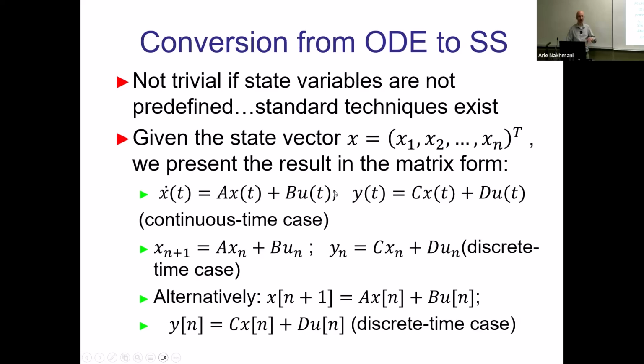This is how we will describe all of the systems, which is practically a system of first order differential equations, okay? You have n differential equations of first order, and all of them are linear. And the output will be computed as some matrix C times that state x, plus some matrix D times input u, okay? This will always be our linear state space system representation.